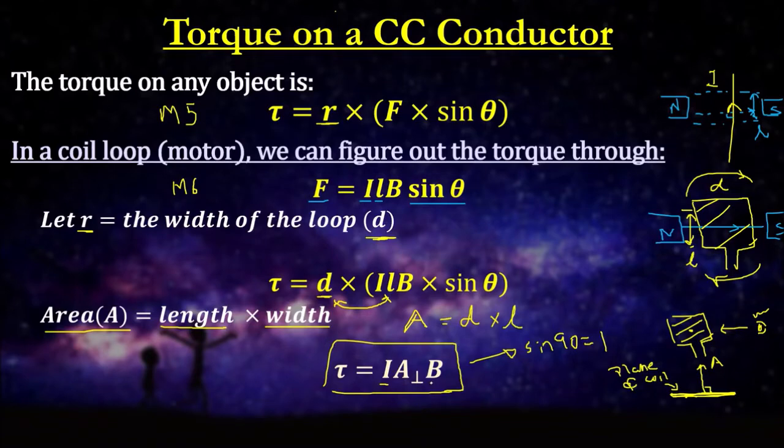And then B, you need a magnetic field. So north, south is what we have here. So three things to make a torque occur. So sine theta there, there's that. If you want to get maximum torque, then that means the area vector here needs to be 90 degrees to the magnetic field. And I'll show you that in a second.